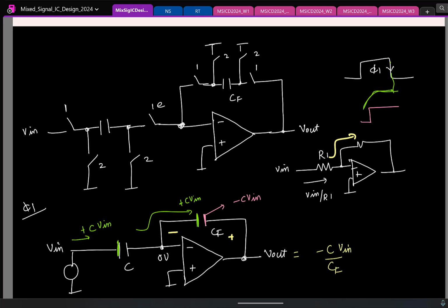So again, in the last class, recollect, we also looked at how to analyze switch cap circuits. Again, to reiterate the point, like any lumped electrical circuit, you can use KCL. That's what you should do. So you write summation over k of ik of t to be 0.